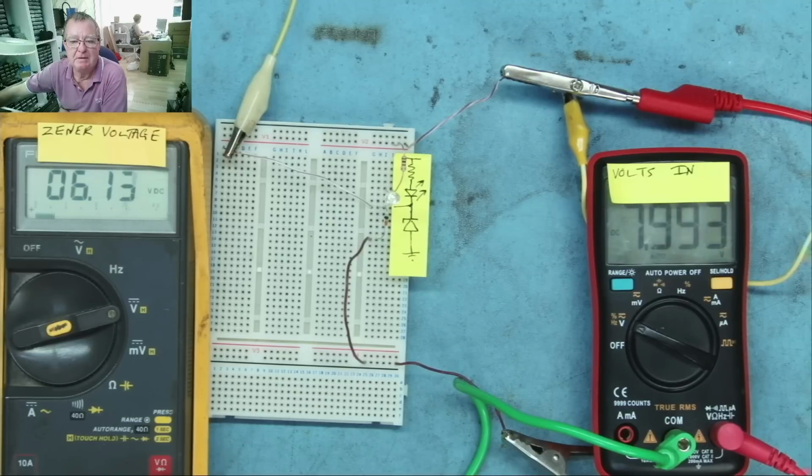We're getting nearer to the Zener voltage now. We still have 6 volts across the Zener. We need to go higher. 8 volts, 10 volts. Remember, this is a 12 volt Zener, so at some point now the Zener will start to conduct. And the LED came on. See that? There. Suddenly. Not just like from dim to on, it basically came on. Yeah, with a very small adjustment.